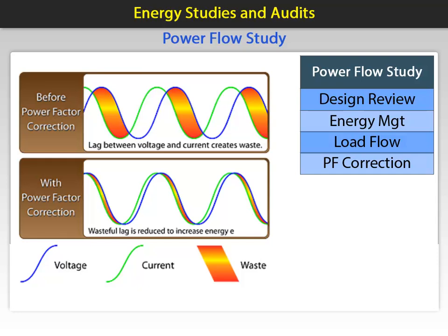Part of the power flow study will measure power factor and reactive power demand using power quality analyzers. It will also analyze load types, inductive, capacitive, resistive, to determine correction needs and simulate capacitor bank placement to optimize correction. The potential solutions might recommend installation of capacitor banks or synchronous condensers for reactive power compensation. It could reveal the use of active power factor correction devices in variable loads. Lastly, an outcome could be to adjust motor loading and replace inefficient motors with energy-efficient models.